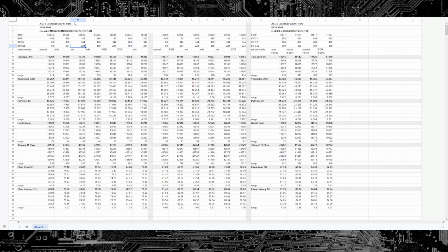basically nothing in common with 16 gigabit M die. And you want 16 gigabit A die, which is the same thing. It has basically nothing in common with 16 gigabit M die. But anyway, we'll get to the overclocking settings later. First, let's take a look at how Expo interacts with the new refresh modes. So, auto on Asus is mixed mode, and we can tell because the performance for them is the same, right?